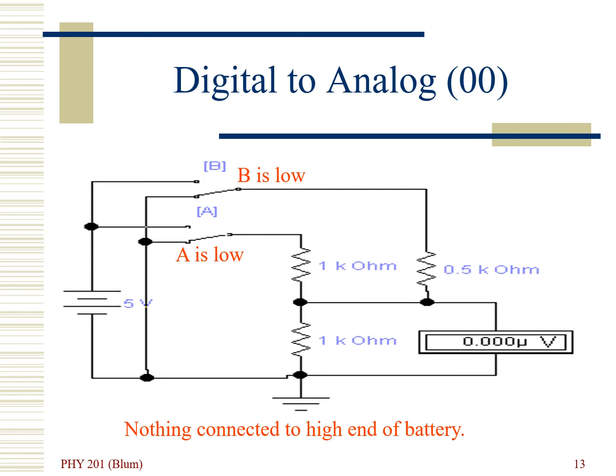Okay, what you are seeing here, I am claiming, is a 2-bit digital to analog converter. It has a 5-volt battery, so 5 is considered our high and 0 our low. We have two switches that are connected to either high or low, depending on which position the switch is in. So we have two binary inputs, A and B, I'm calling them.